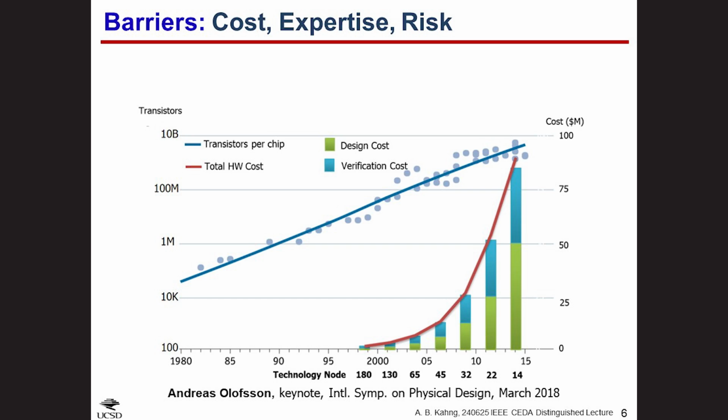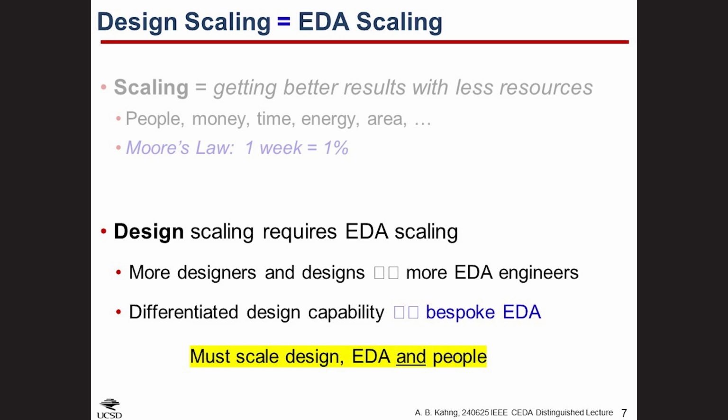Okay, so what about EDA itself? Very important. Sorry, I say this every chance I get. The heart of EDA and IC design is optimization. Do better, always. So in this cartoon, there's an input like RTL, constraints, libraries, tech files at the flow start at the top. And there are many steps and decision points like density screens or path groups or pin placements on the way to a complete outcome, which is your routed chip plus sign-offs, which is the flow end leaf.